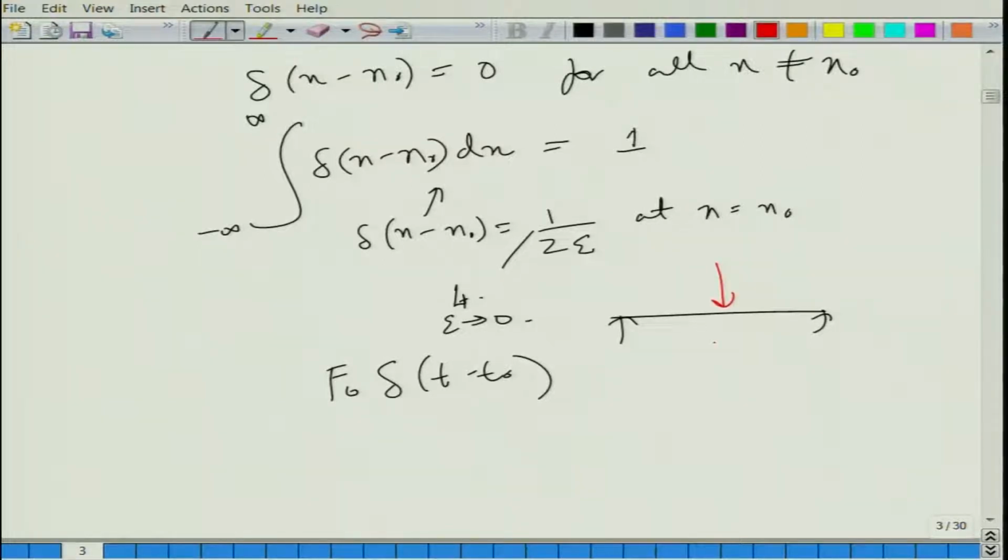So, if you have a beam something like this, you can have a point load force acting in this direction. This is modeled by a Dirac delta function, a point excitation. In which case you will have this additional e to the j omega t term, meaning that there is a harmonic excitation force, but very much localized in space at a single point.